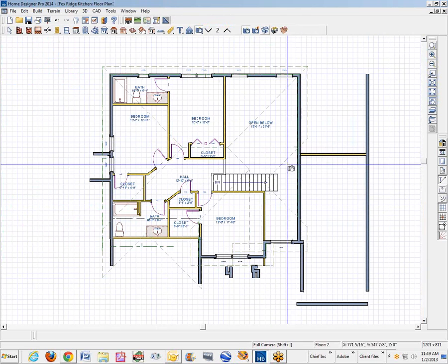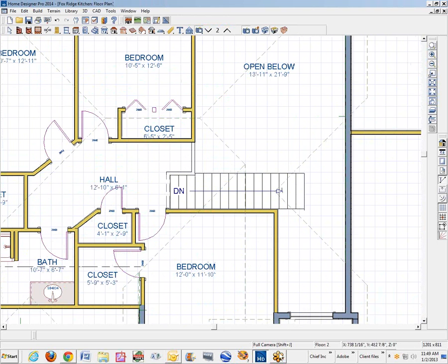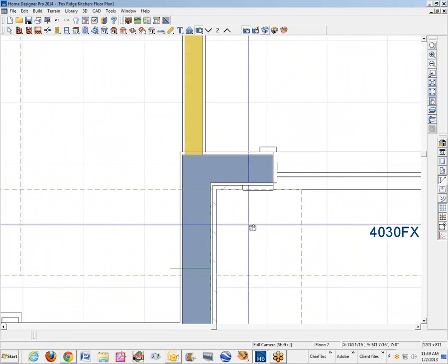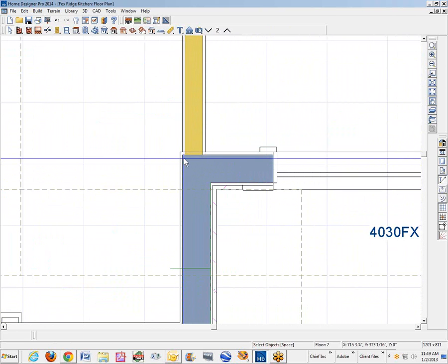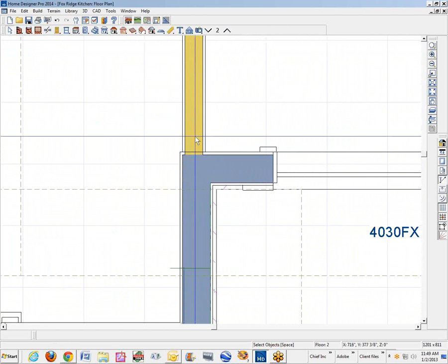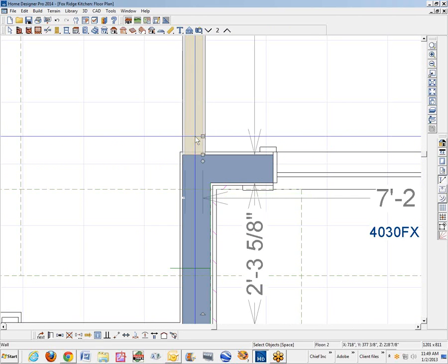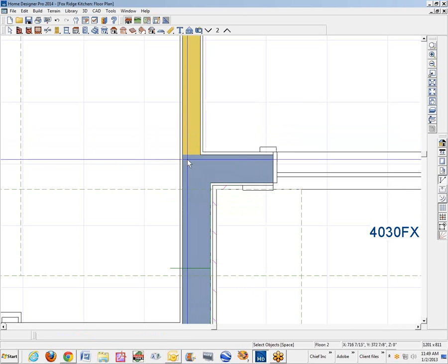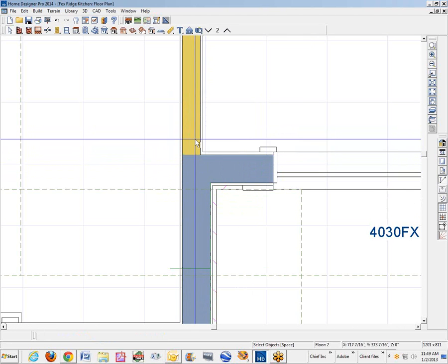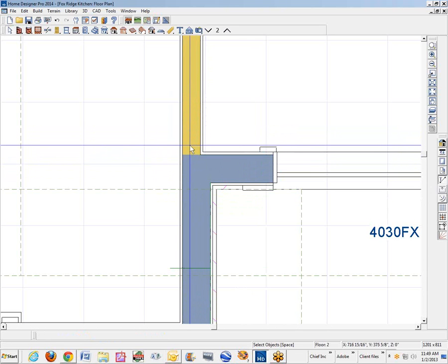Now, when I came up, I tried everything. I made sure that, oh, let me show you one thing I found. You would look at it and say, well, that's no big deal. This wall's not properly aligned with this wall. That's something I noticed right away. Just pull that over and let it snap in there. Now that's properly aligned. Little things like that will add up and make your model unstable.